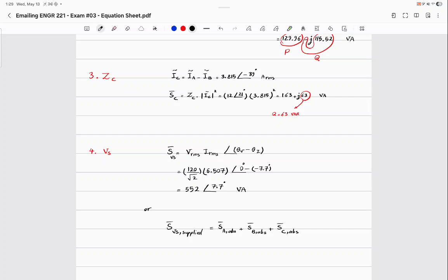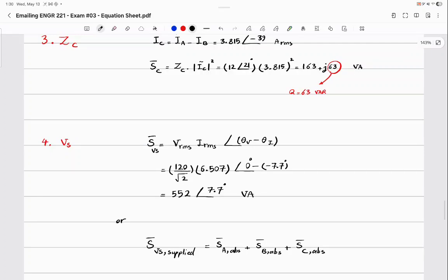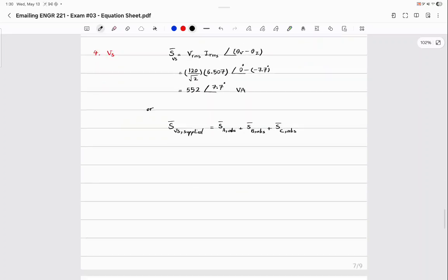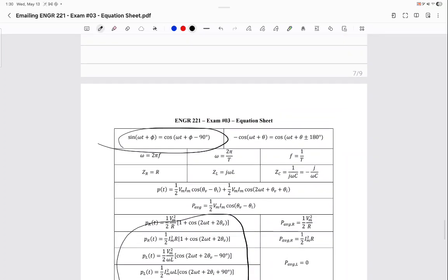Yes? So why can't we have the main current coming out of the source? Did we find that? Can we just multiply that by the VRMS, just like IV, and you get the same thing? You don't get the angle. So we'll just plug in 0. Oh, it only works because it's 0 for the direct current source. Yeah. Okay. What you're saying is not wrong, but you have to be careful to add the angle to the number to make it complex, and the angle is the voltage angle minus the current angle, right? Any question?